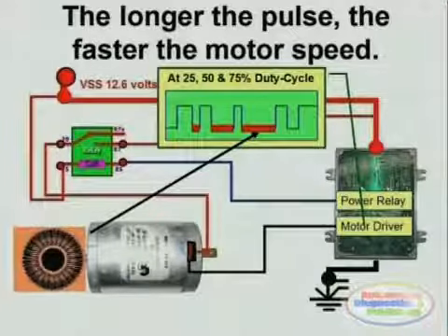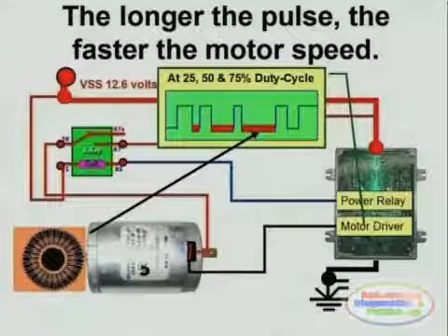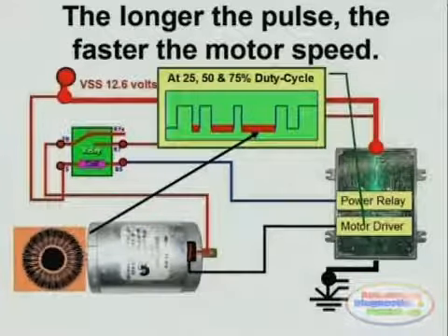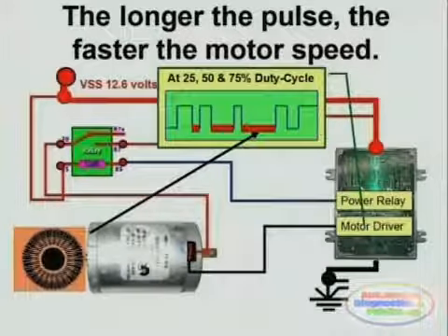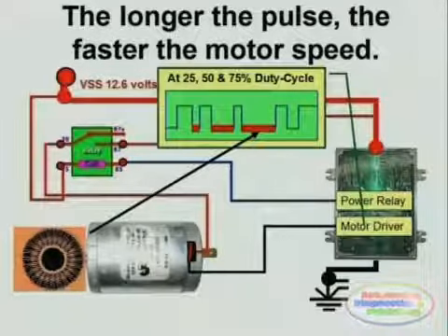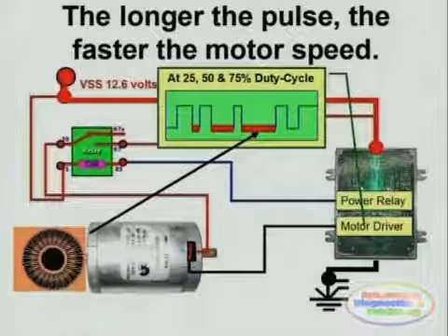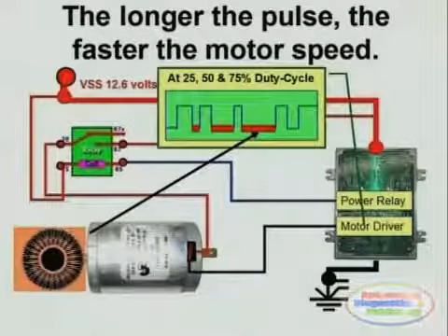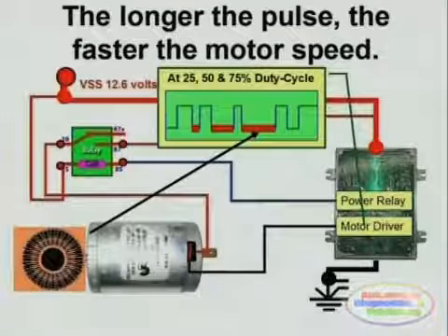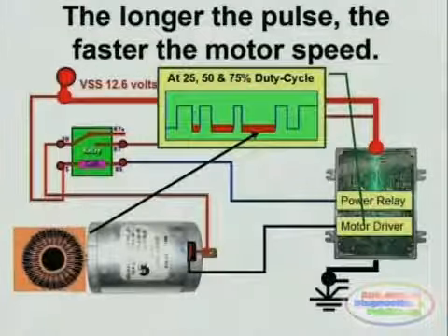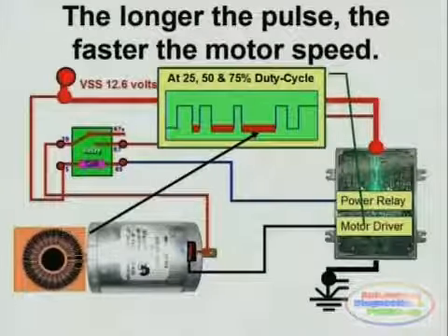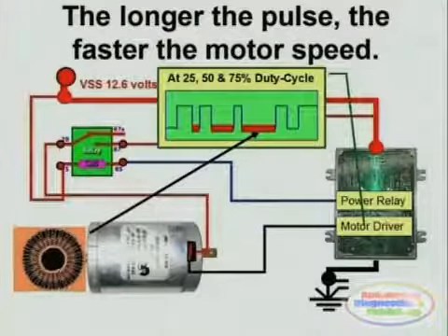The output of the controlling circuitry is going to be determined by the width of the pulse that is applied to the base of the transistor that is doing the controlling. This pulse is modified by the microprocessor through its internal circuitry, and again the microprocessor, through the transistor driver, determines the speed of the component being controlled.